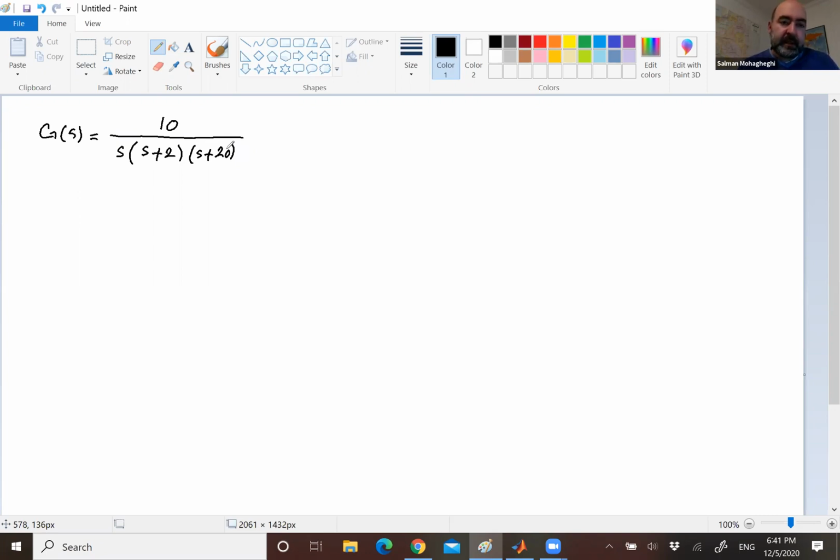And let's say the desired characteristics of the system for me are rise time of 1 second and overshoot to be less than or equal to 10%. This is what I want to achieve. And we'll first start with the easiest controller, which is a proportional controller, to see if there is a gain k with which I can achieve these two characteristics. Let's translate these into system parameters.